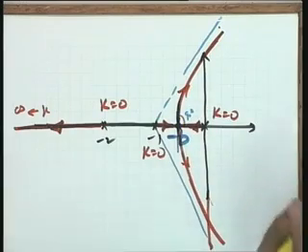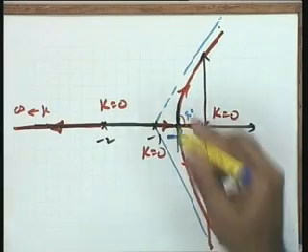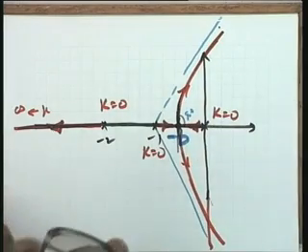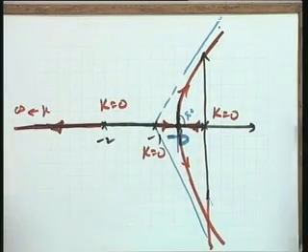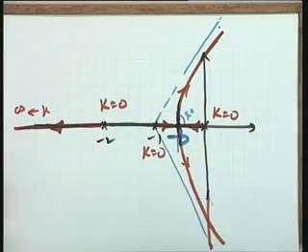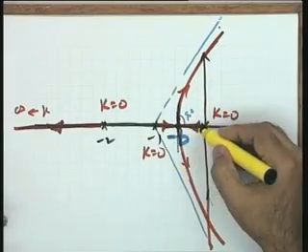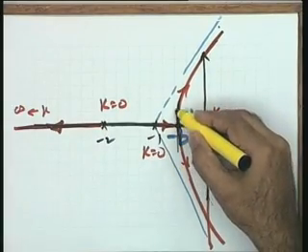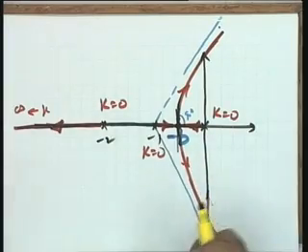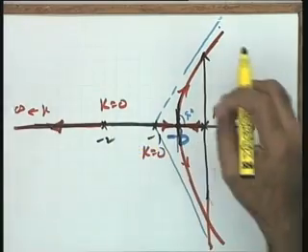You will find that the angle criterion requirement says that this particular angle will be 90 degrees for the angle criterion to be satisfied. Okay. So it means if I know the point minus B, which is the breakaway point, you see the situation becomes a very happy situation, because I can take this point, take an angle of 90 degrees and then an asymptote to this, I will be closer to the actual sketch.